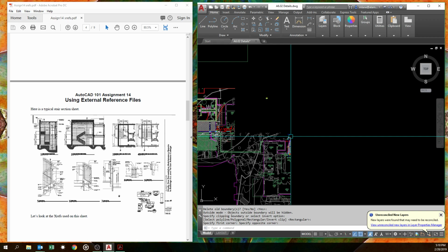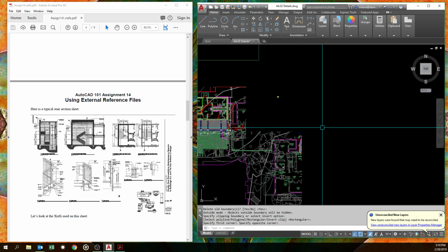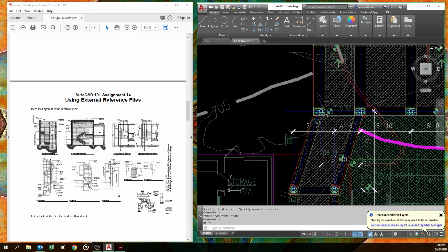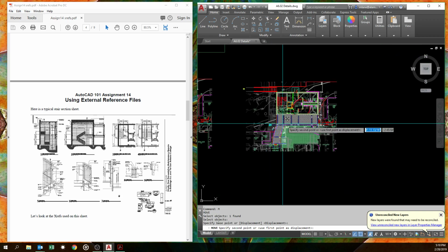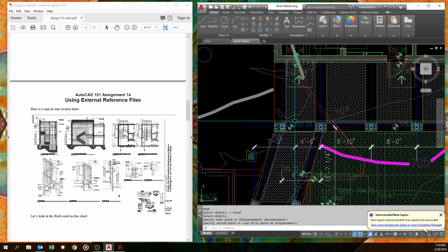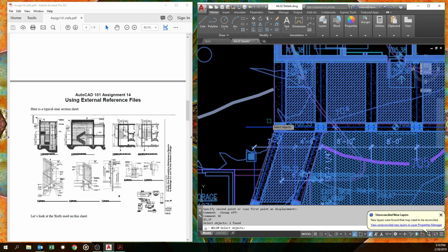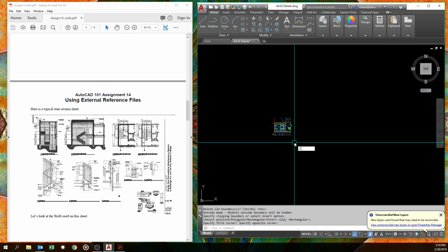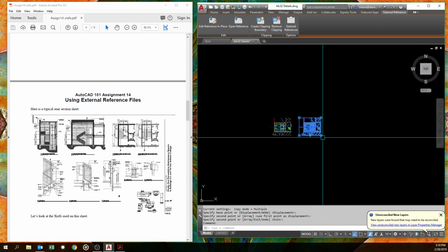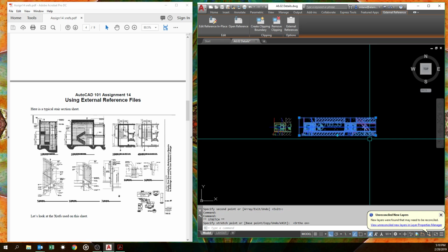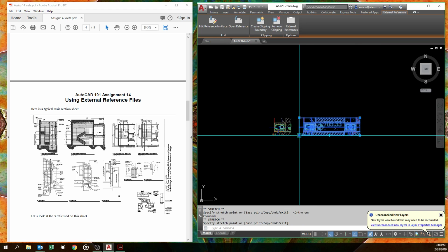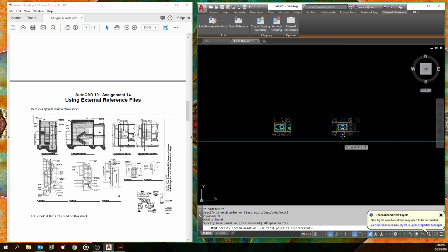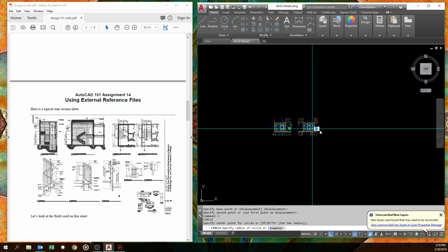And it jumped to some weird object snap. Let's try that again. We love AutoCAD. Let's get it away from the other one some. And we'll turn my snaps off. So XCLIP this thing, new, yes, rectangular. You notice I'm doing that with the right click of the mouse. I don't actually have to hit the enter key. All right, and copy. And of course that's not the one I need, but the one I need is right over here. And then I have that highlighted, so I just move it. Copy, whoops. Using my C shortcut for copy.